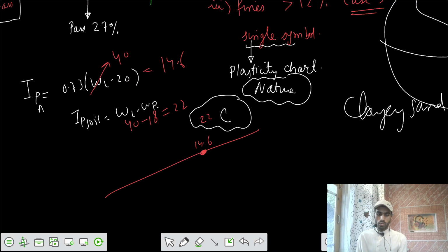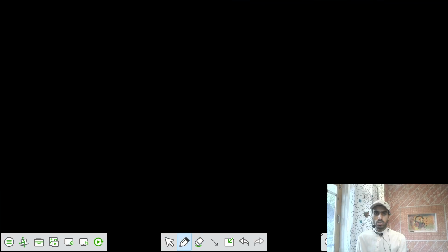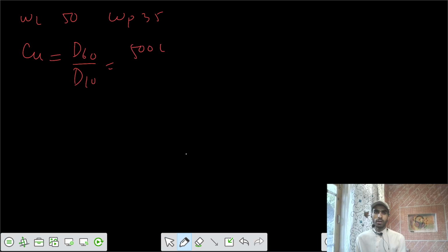Let's take one more. Let's say that we have liquid limit 50 and plastic limit 35. Let's say that Cu can be calculated as D60 by D10, and let's say this is 500 micron by 1000 micron.